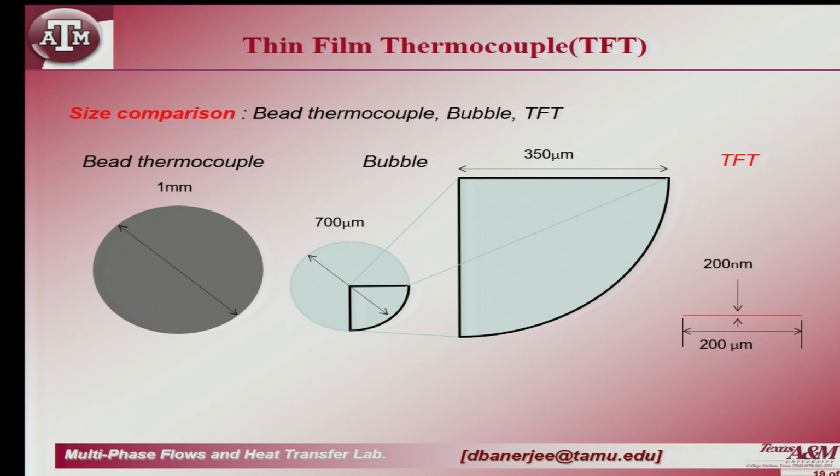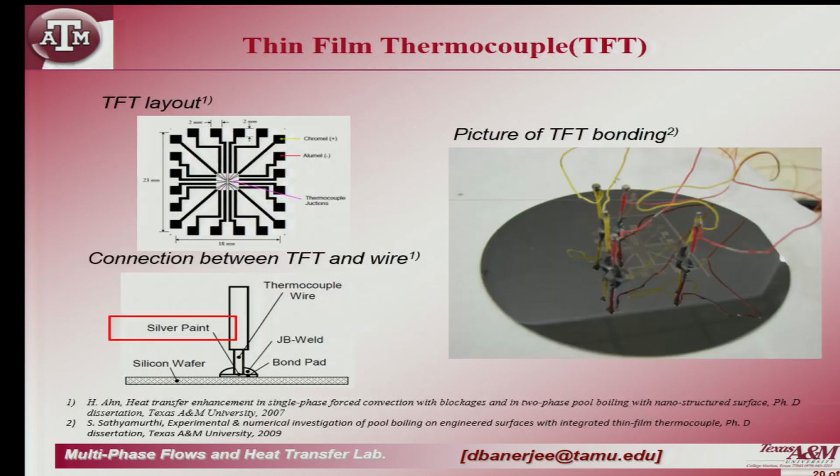All right. So, next thing is we wanted to make these nano thermocouples. So, we made a nano thermocouple. What is a thermocouple composed of? If I am using a K type thermocouple, I have a chromel wire, okay, and what else do I have? Alumel wire. Okay. Chromel is, I think, about 90% nickel, 10% chromium. Alumel is about 70% nickel. There is, I think, 10% aluminum and a bunch of other things. Okay.